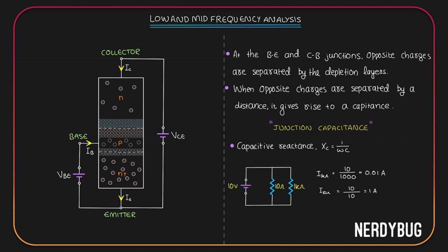Now imagine instead of the resistor, we have a capacitor there. It has a capacitance C. But in the first video of this series, we have learned that the property of a capacitor that is equivalent to the resistance of a resistor is not the capacitance, it is the capacitive reactance. Now, if the capacitive reactance is too large, you can ignore the capacitor just like you ignored the larger resistance in the previous case. It will not affect our circuit at all.